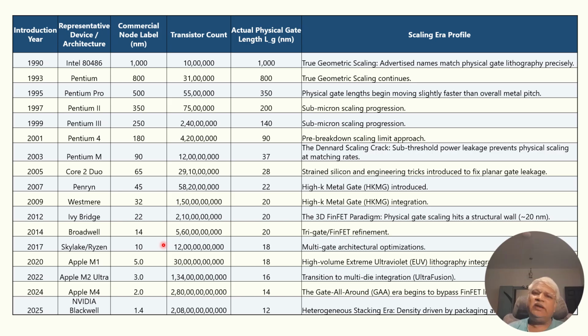The metal layer types also changed, that means multi-patterning, the pitch of the metals and poly pitch, and 3D architectures of the IC. So innovation started popping up in different places, and the difficulties associated with miniaturization and short channel effects have been alleviated.